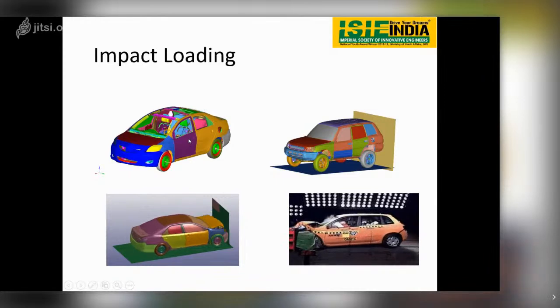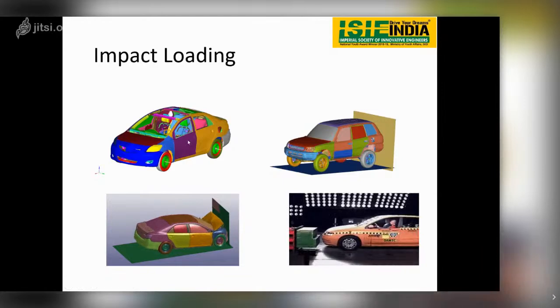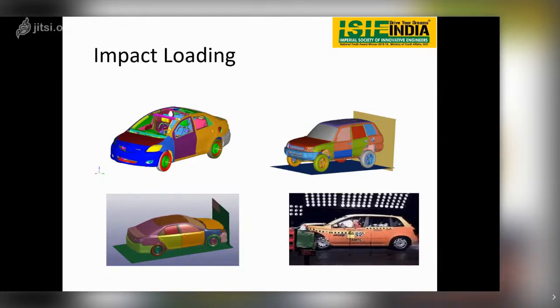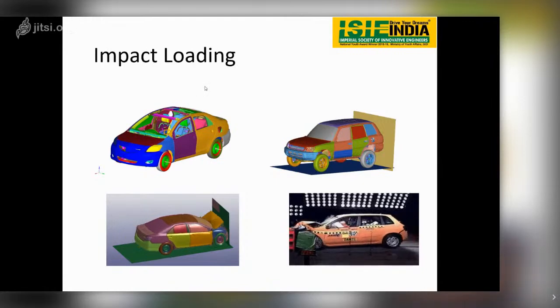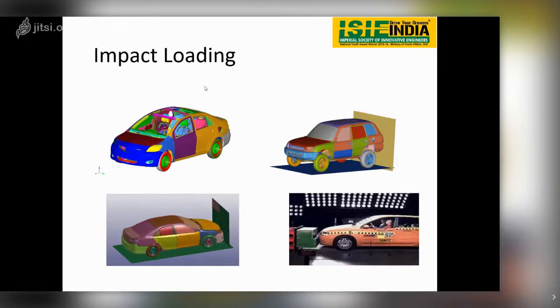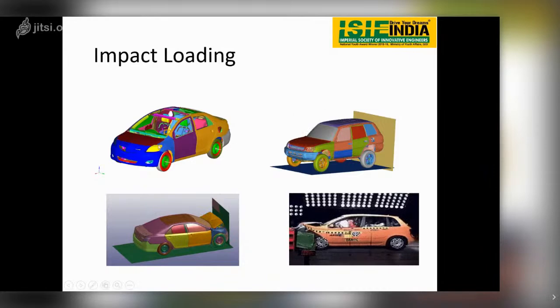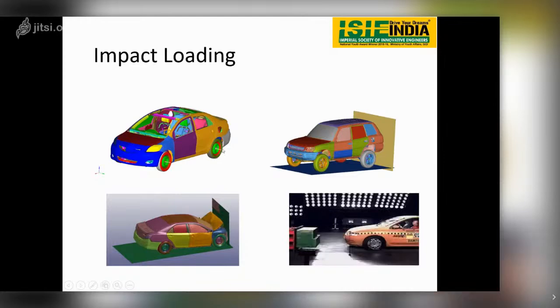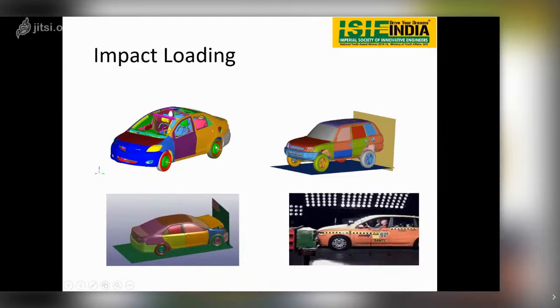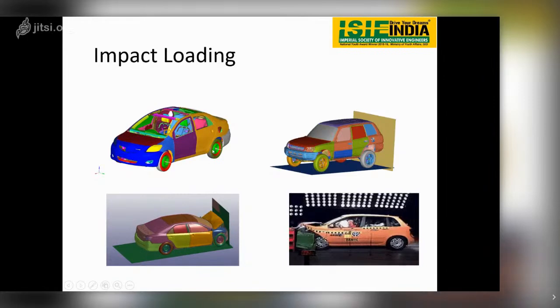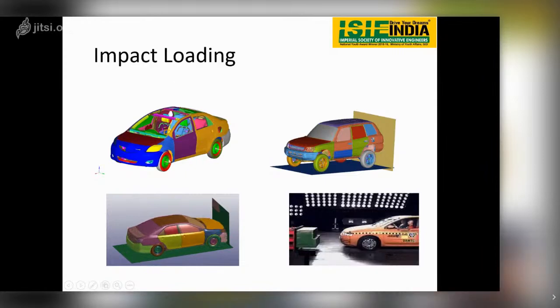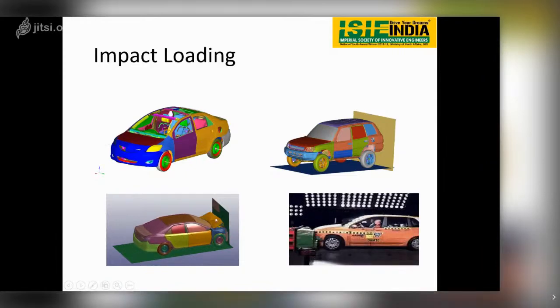And then we should define the kinematics of the system very well. To define the kinematics, we need to give the joints, so there will be different kinds of joints like spherical joint, revolute joint, universal joint, and so on. Here we can see in the tires we have defined the revolute joint, so the tires will rotate about this. After giving the exact material properties, mass and properties are checked, the loading condition is applied and it is made to strike over here.